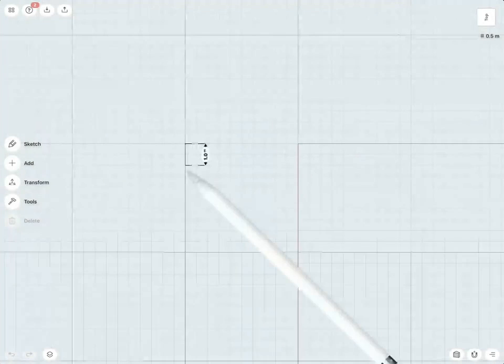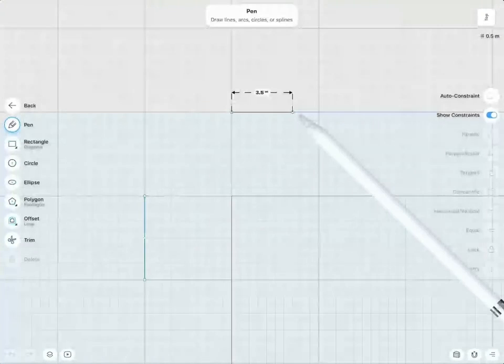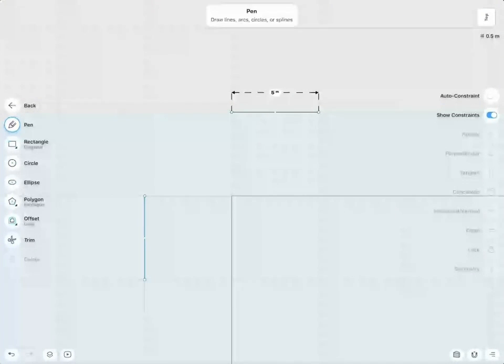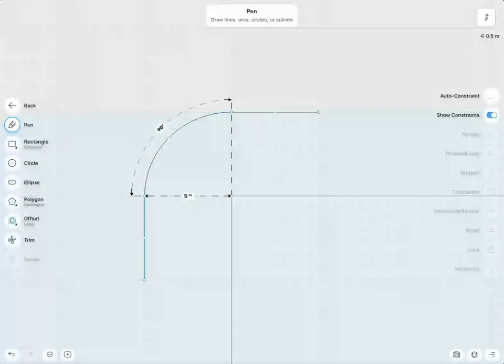So we know when we want to create a pipe that goes around a 90-degree corner, ideally we want to have a layout like this, and then we can put an arc in between. I could select the line and arc, and do the tangent. I skip this step because by using the grid, I know the arc and lines are all tangent to each other, which is a very good reminder to really make use of the grid. So the grid snapping, very good. So that looks pretty good.